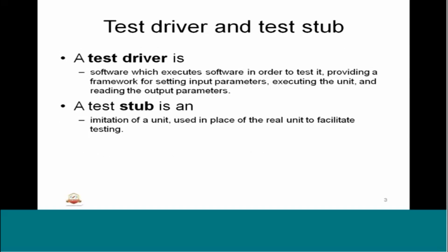Also, we studied about test driver and test stub. It's a very important part of embedded software testing. Test driver is software which executes software in order to test it, providing a framework for setting input parameters, executing the unit, and reading the output parameters. So basically, the test driver will invoke the unit which we want to test.